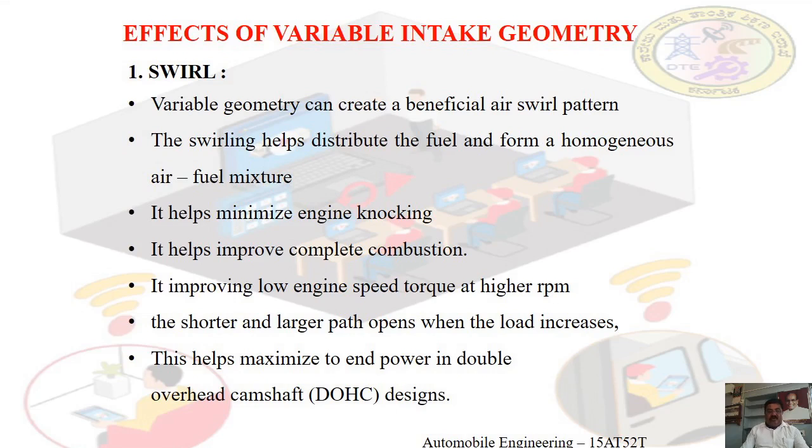At low RPM, the speed of airflow is increased by directing the air through a longer path with limited capacity, and this improves low engine speed torque.